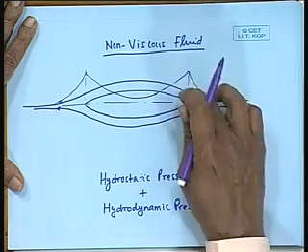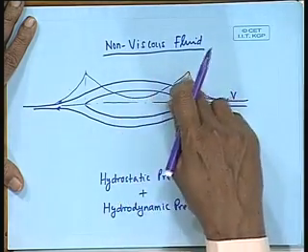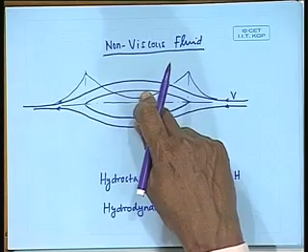Am I clear? So, if pressure increases, velocity reduces. Now, we are ignoring the hydrostatic pressure, only talking about dynamic pressure, then only this is valid. So, if the pressure increases here, the velocity drops, and as the pressure reduces, velocity is maximum at the midship region, and then the velocity has to come back to the normal value. So the pressure has to increase, velocity has to reduce.